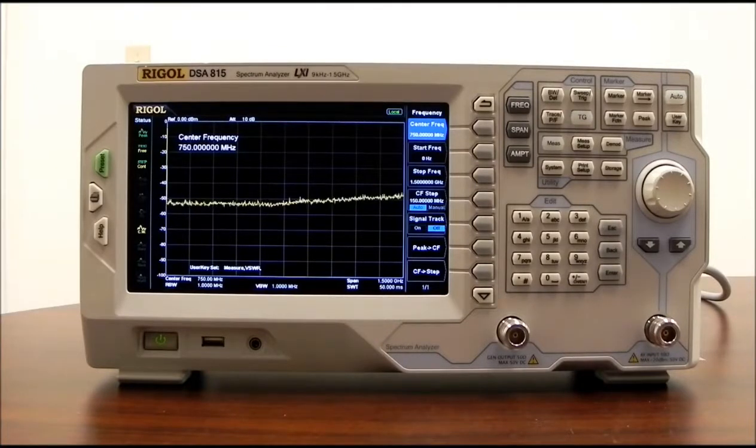Some typical applications are monitoring RF or radio communication channels. How much bandwidth a particular channel may be taking up is a pretty common example. Measuring filters if you're designing radios, or you're using filters to help clean up some of your signal levels. You can then characterize the filter with respect to frequency using a spectrum analyzer and a tracking generator, which we'll get into a little bit later.